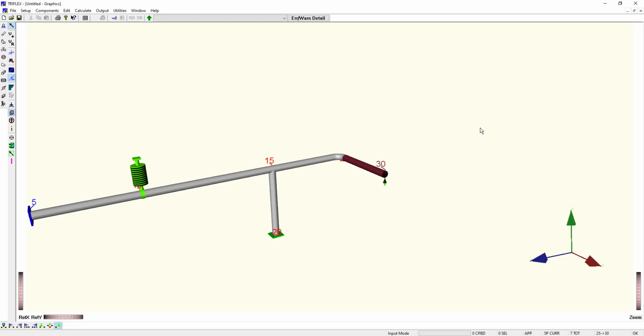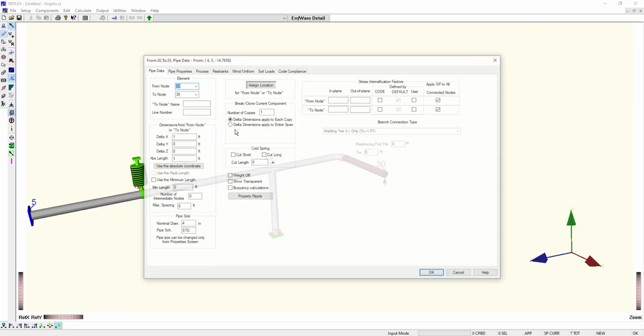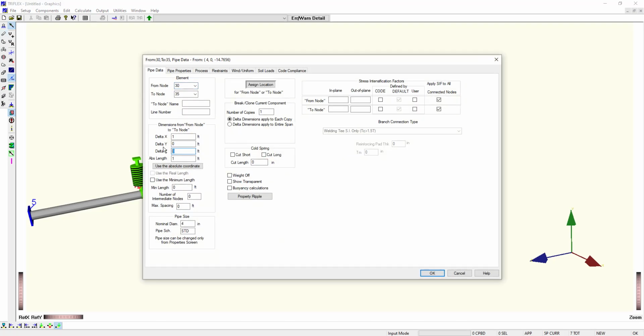Okay? Now we're going to go in this direction, that's the minus Z again, with a pipe and an anchor. So we're going to pick up a pipe, head into the minus Z with 5 feet, 2 inches, and 1/8 inches.